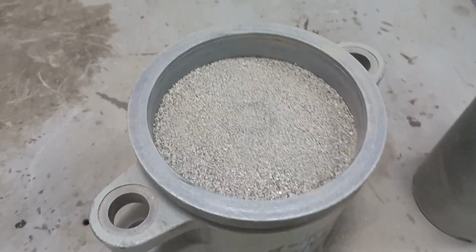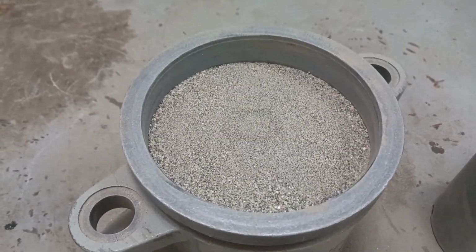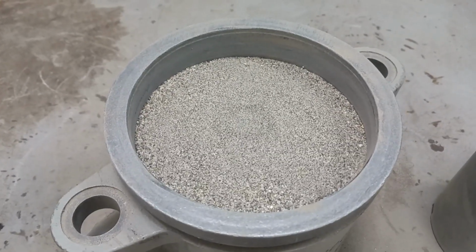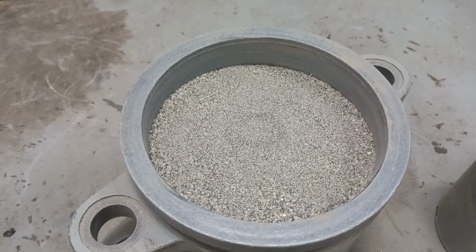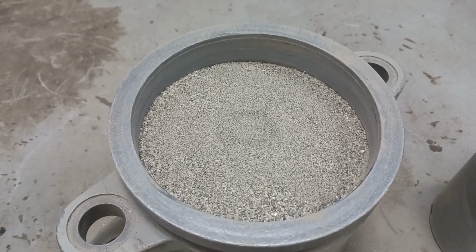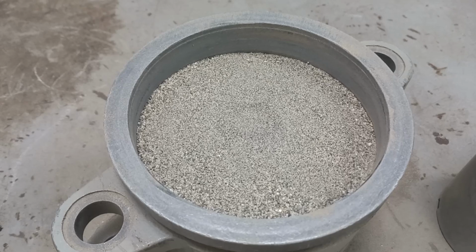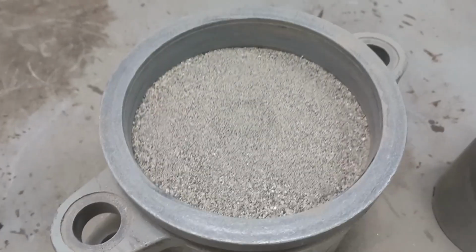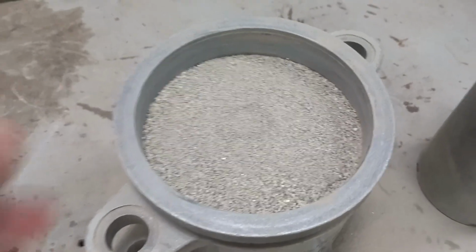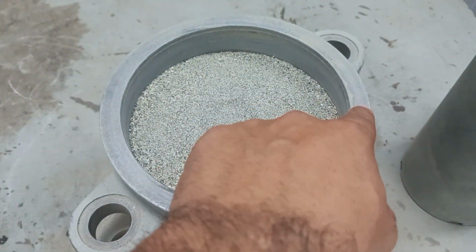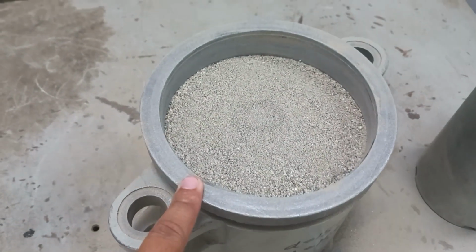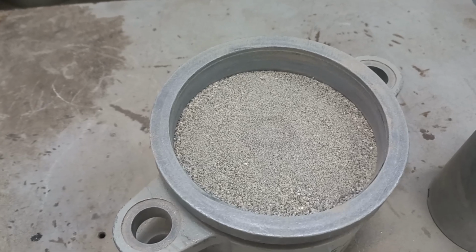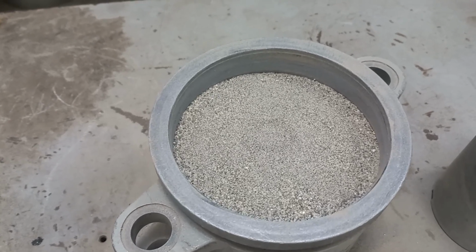Now you can see that there is a decrease in the height of the sample that was filled in the mold up to the top of the mold. This decrease will be measured with the help of the vernier caliper or dial gauge. We will measure this decrease in height with the help of the vernier caliper. We will take 3 readings at 3 different points, and an average value will be taken on the basis of these 3 readings.